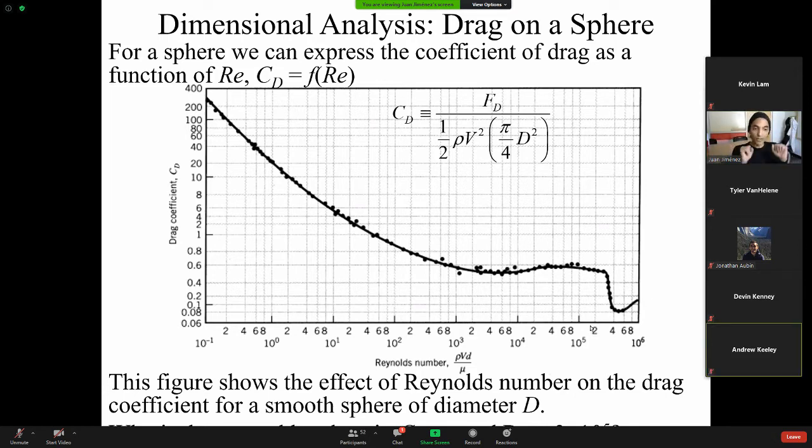Yeah, absolutely. So keep in mind that the boundary layer for a little portion is going to be laminar when it starts, but then eventually develops to turbulent. So that's how we characterize it. Even if for a micron or a millimeter at the beginning your boundary layer is laminar, if it transitions to turbulent, we're going to call this a turbulent flow. If it stays in the laminar regime the whole time, laminar flow. All right, cool. Thank you, Andrew.